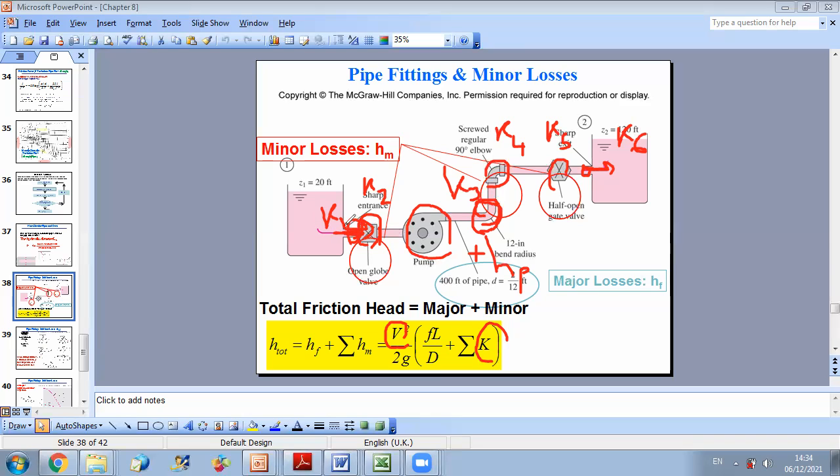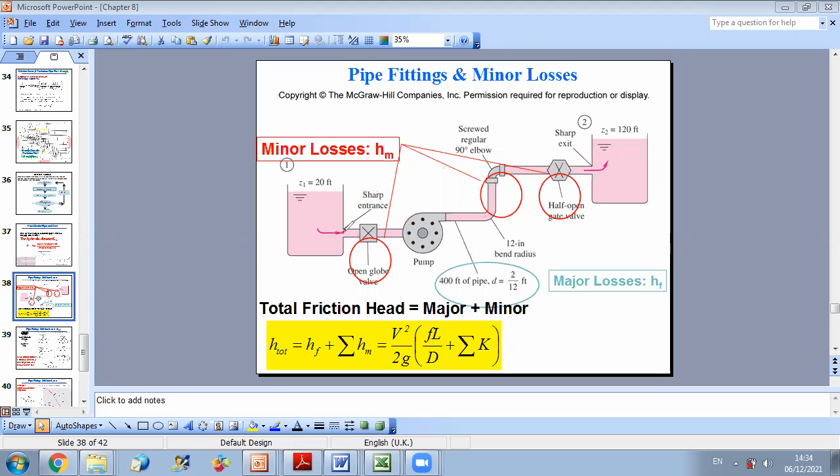But now I'm telling you, whenever you have an inlet, K is multiplied by the velocity after the contraction, because here you have a large reservoir and suddenly you have motion in a duct. So you multiply K for an inlet by the velocity after the inlet, while for the exit, you multiply K by the velocity before the exit. Here it's a common velocity V. This is why we have considered it into account, because the cross section, from this point to the end point, has exactly the same velocity.